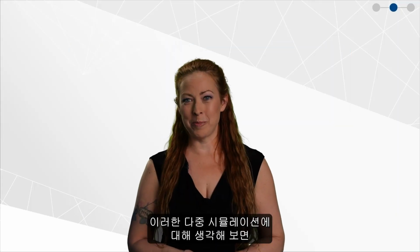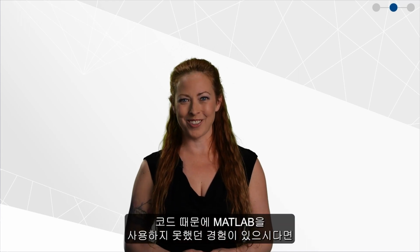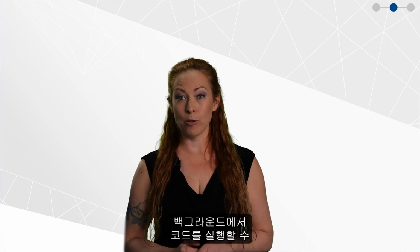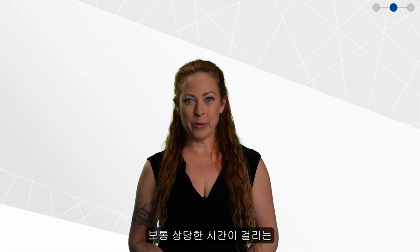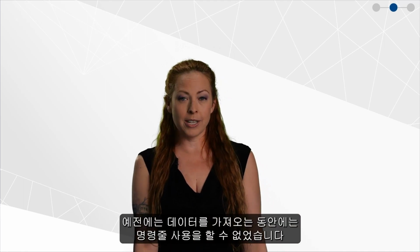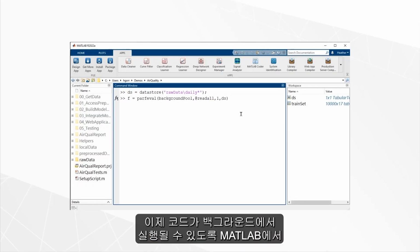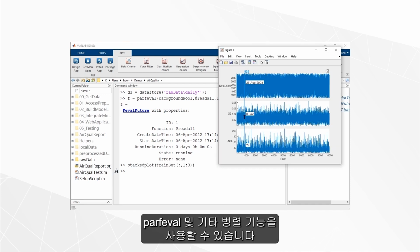Thinking about those multiple simulations reminds me, if you've ever had MATLAB blocked by some long-running process or code, you're going to love this next update. You can run code in the background through multithreading, which was introduced in the last release. Here's a great example of importing lots of data, which normally would take a long time to run. And during that time, the command line would be blocked. Now you can use parfeval and other parallel functionality in MATLAB, so the code can run in the background.